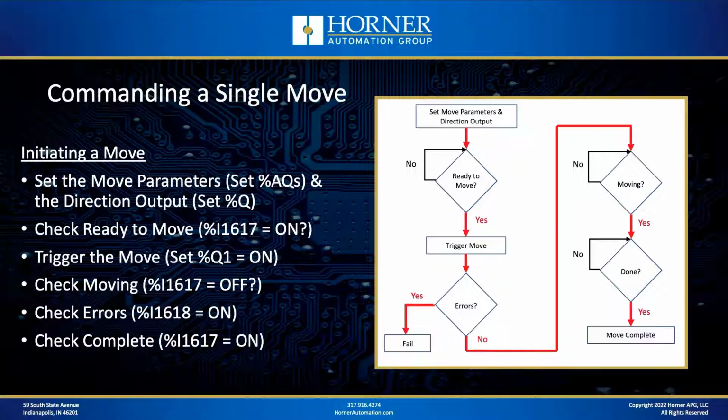When it's on, it may go clockwise. When it's off, it may go counterclockwise, or vice versa, depending on the motor and the drive combination. But because the direction doesn't change very often, you can use just one of the standard solid state outputs, somewhere between Q3 and Q12, for instance, as your direction output.